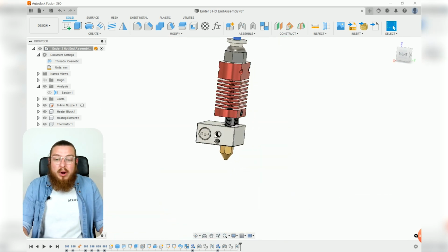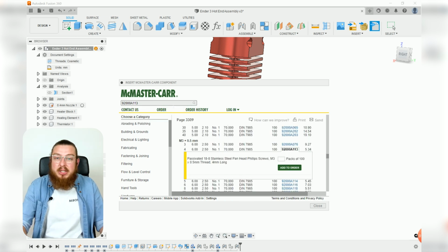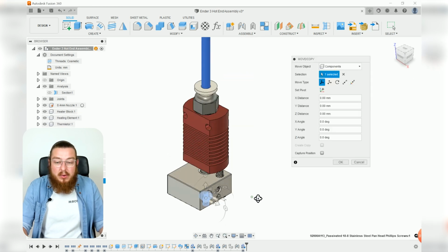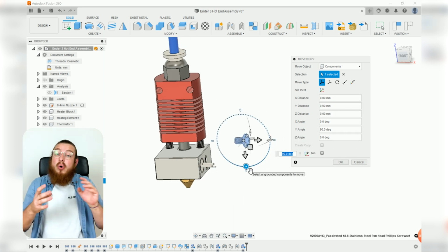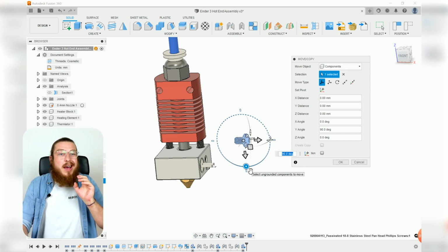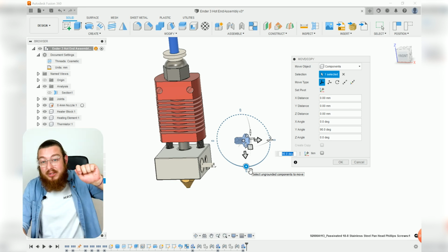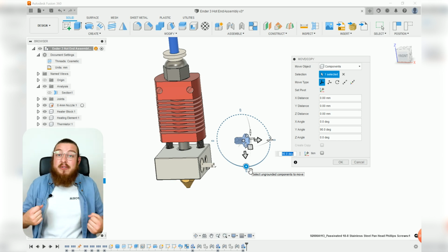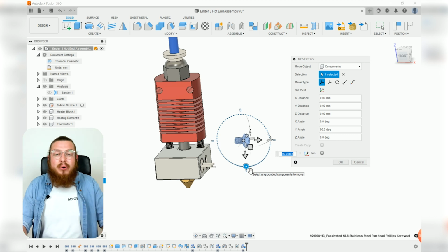Great. We've got a random one-off screw right here. The screw that we have is a very strange, kind of stubby Phillips head bolt. It's again another M3 thread, but this is a really funky one because it's not being held in super duper tight. It is going to be there just to hold that glass bead, a little thermistor in place, and if we tighten it too tight, that'll actually interfere with the resistance of the wires that go into it. So if you really over tighten it, it'll give you a big error saying thermal overload or thermal runaway, saying there's too much heat going on, I can't get any information back, I don't know what's going on, big errors. So this is just lightly tightened in, just so it kind of holds things in place.